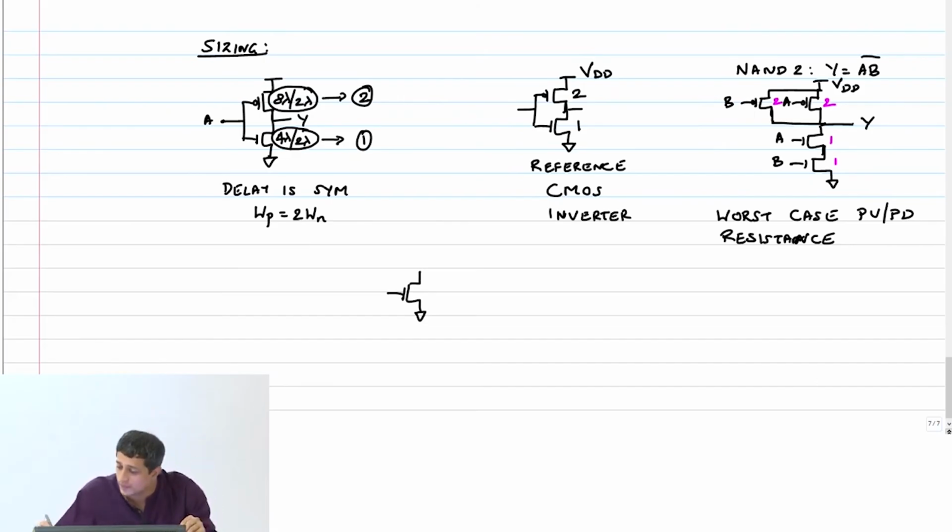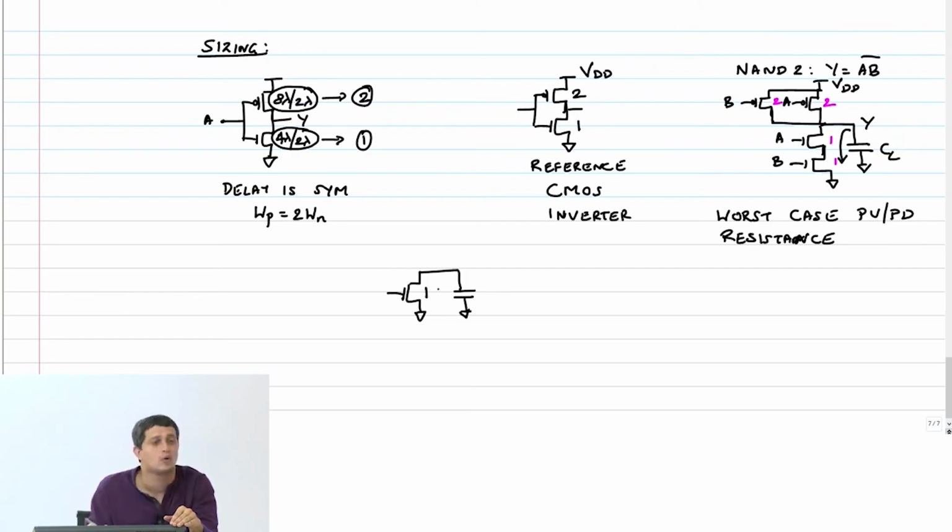Let us assume that a capacitor here is being discharged. It has VDD initially, and that is now being discharged through this pull down stack, right? I want to look at the worst case resistance that will be offered by that stack, and ensure some constraint on that. Okay, so first let us look at when we had a single transistor with size 1, unit width 1.